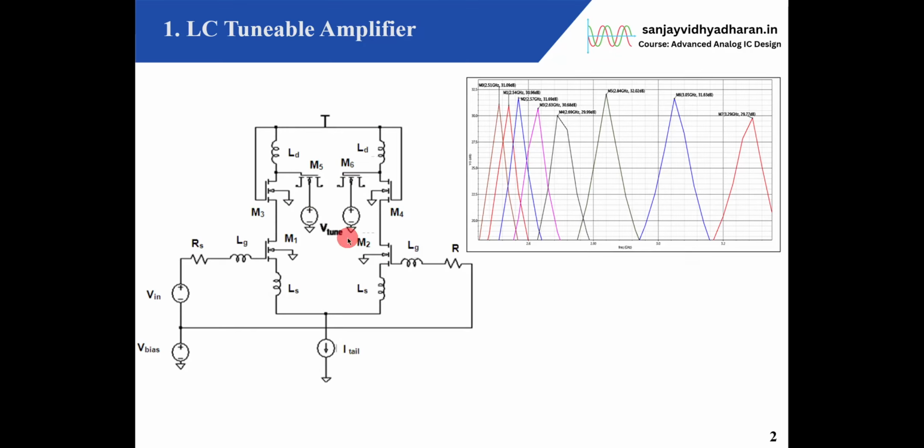So this was the tuned circuit which we discussed in the last class, where we wanted an amplifier which amplifies only the required signal, and then we used a PMOS. It is essentially an LC circuit. So omega equal to 1 by root LC will decide the resonant frequency, and only that particular frequency will be amplified. L is fixed here, and instead of C, we used a variable PMOS. So this is what we learned in the last class, right?